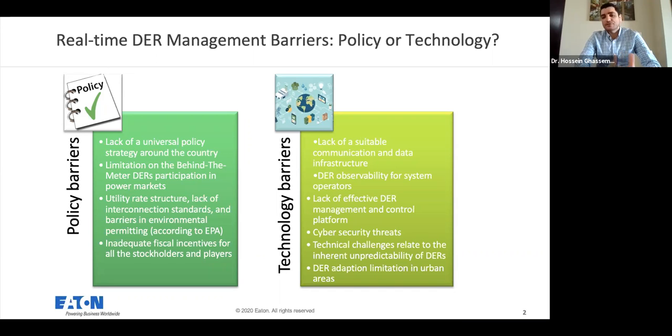And when it comes to the power system, specifically at the distribution level as well as the secondary network, we are still facing a lot of limitations, and utilities see DRs as a burden rather than a tool to take advantage of these new technologies. For example, in urban areas, the IEEE standard today and the practical approach utilities have is that they would not allow any reverse power flow because of the protection limitations in urban areas. Those limitations will limit how much DR we can put in the system.